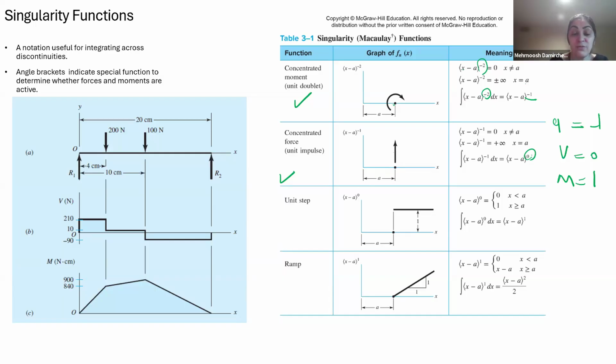Now, the problem that we solved before, in this video we want to use the singularity, and it is easy. Look at here. We have one R1 applied at x = 0, so instead of x minus a, here should be x minus 0, so it is x. It is R1. What is the power? It should be -1. I agree. This 20 should be -20. At which point is it applied? At 4, and -1. Again, -100, x minus 10 to the power -1.